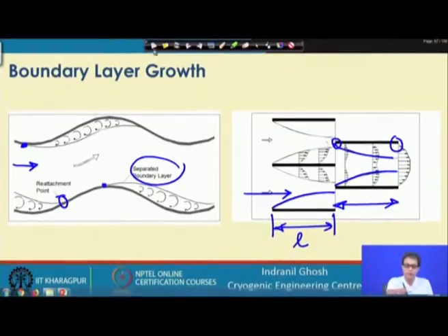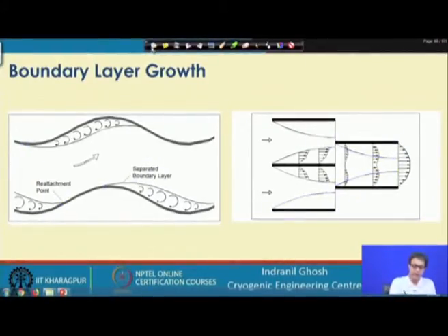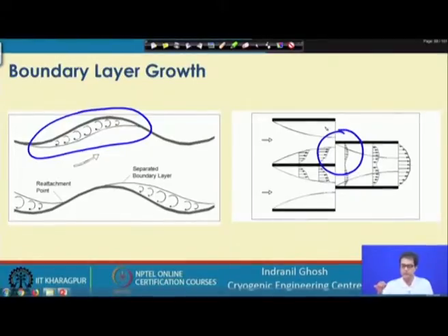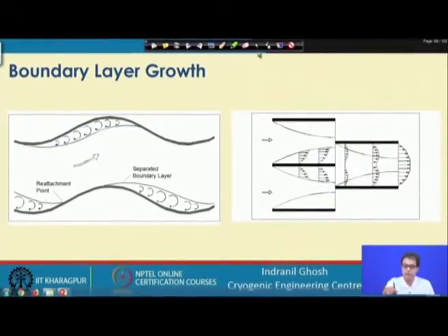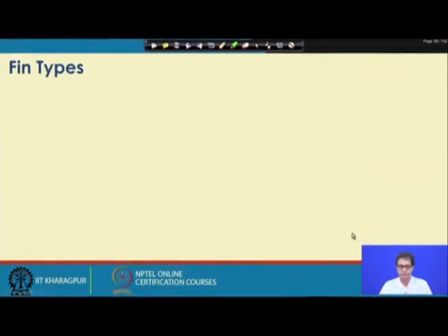Okay. So, in this one the pressure drop penalty is a bit less as compared to this side, but particularly when we go for a very high heat transfer rate, we look for this offset strip fin, and this is in regular use in different kinds of plate fin type heat exchangers.